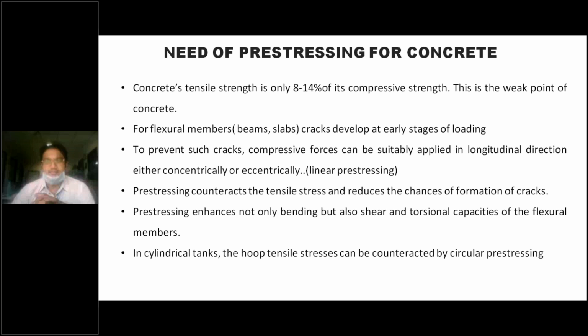One more thing, pre-stressing counteracts the tensile stresses, and it reduces the chances of formation of cracks. As we know, concrete is weak in tension. With the help of pre-stressing technology, the concrete can reduce the chance of formation of cracks. And one more thing, pre-stressing enhances not only bending but also shear and torsional capacities, in terms of flexural members, right? So this is the way pre-stressing enhances bending, shear, and torsion with the help of this technique.